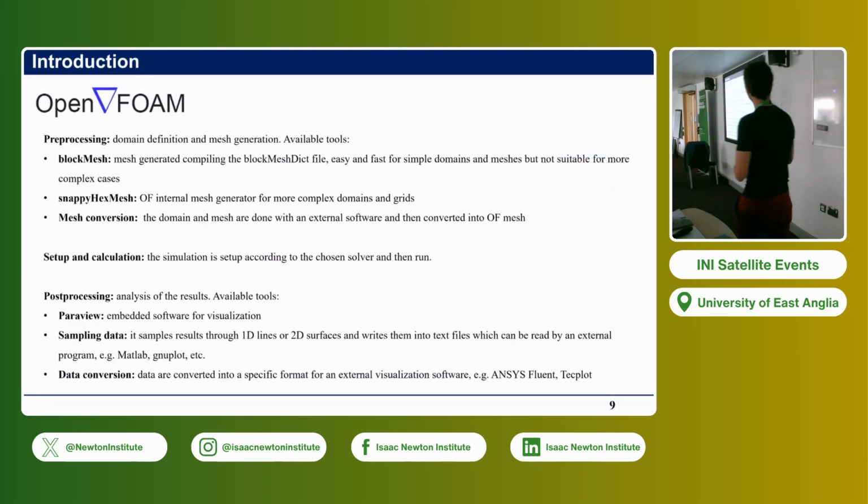Now, OpenFOAM comes with pre-processing utilities where you can make simple meshes on cubic or rectangular square domains, but you can actually import more complex geometries, for example, to study flow around a car or whatever you want, and you would use snappyHexMesh, which is a bit of a more sophisticated mesher for OpenFOAM. You can also make your mesh somewhere else, for example, with Salome, and import it. These are all the solvers.